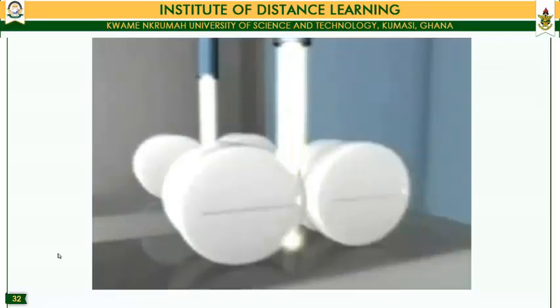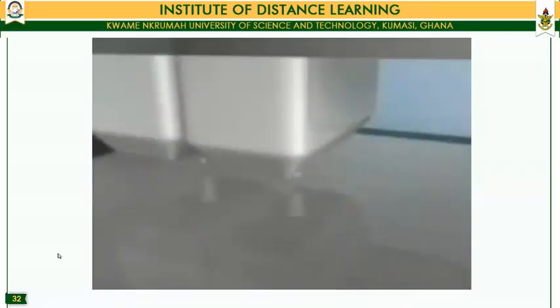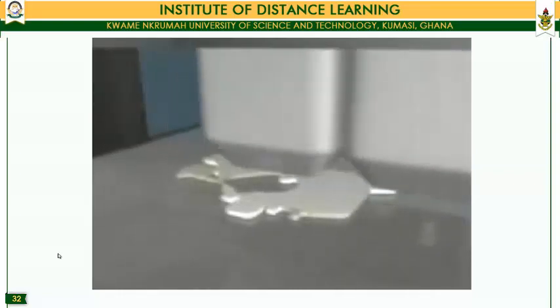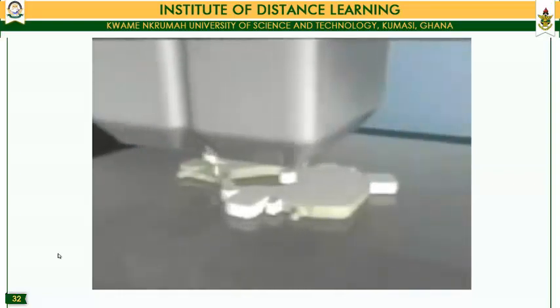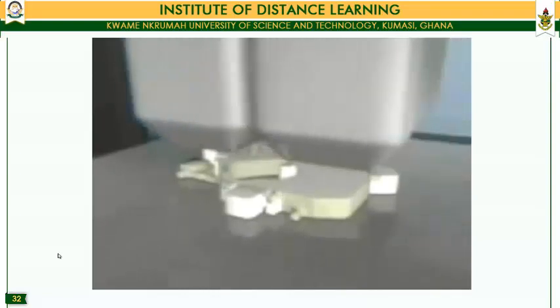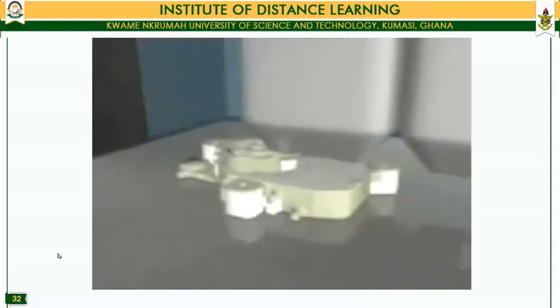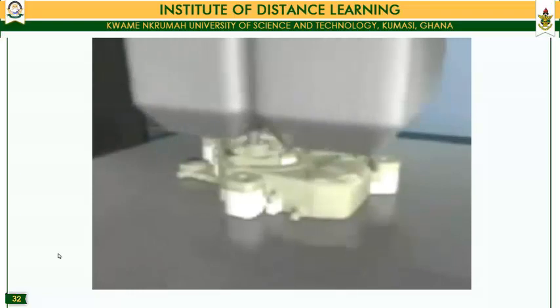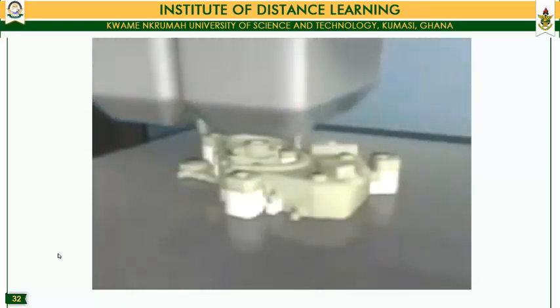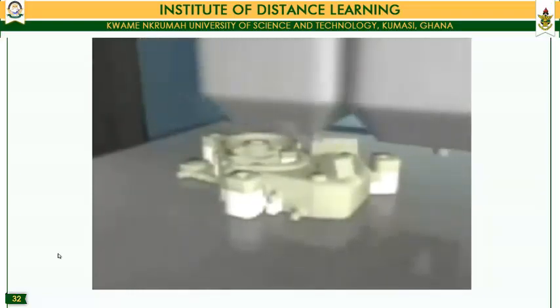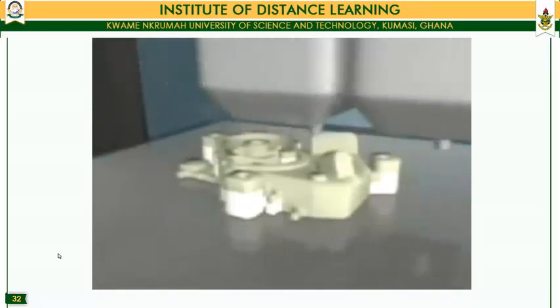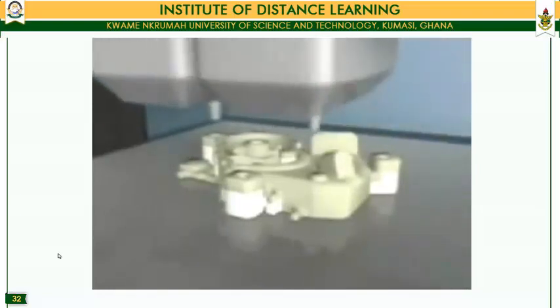Inside the system's heated build envelope, model material in filament form is heated to a less viscous state for extrusion. The model is built layer by layer from the bottom up. On each layer, the extrusion tip follows a precise tool path created by the Insight software, extruding thermoplastic modeling material along with any necessary support structures.